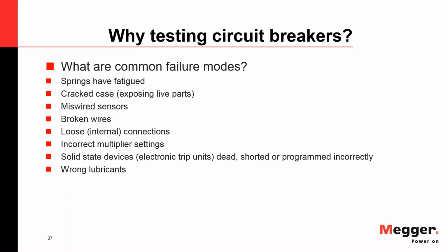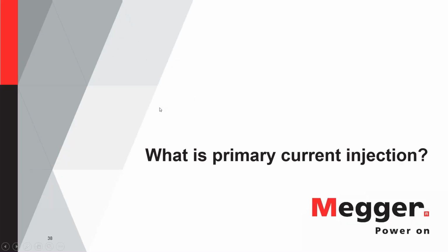People are doing maintenance, putting on the wrong lubricants, and everything now is kind of gummed up, if you want to, or they use WD-40, a classic, which is not a lubricant, and introduce corrosion to the mechanical system. All of these things can happen.